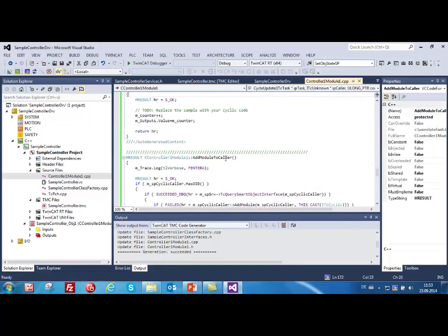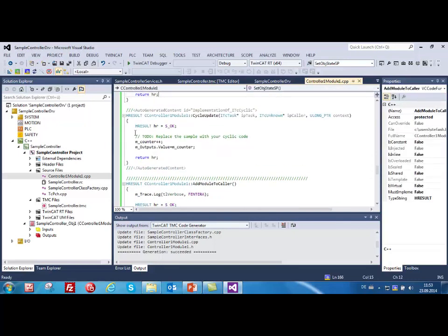Here we go, and just put this in brackets and ask: if bRun is true, then do the execution, otherwise not. So you have something which is cyclically called from the outside world. Yes, that's true, but internally your code is only executed in case execute was set to true before.